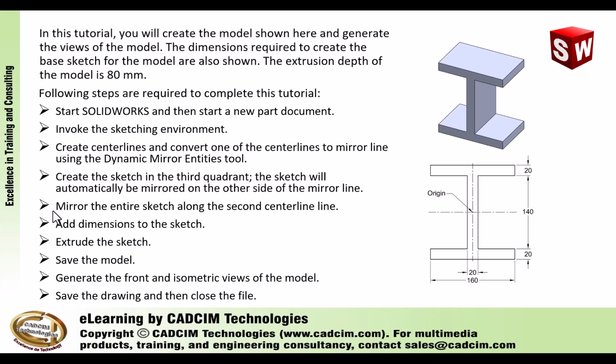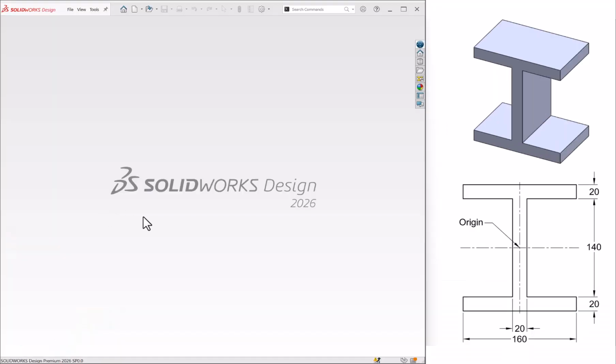After that, you will mirror the entire sketch about the second center line. Then you will add dimensions to the sketch and extrude the sketch to a depth of 80 units. Then you will save the model and generate the front and isometric views of the model. At last, you will save the drawing and then close the file.